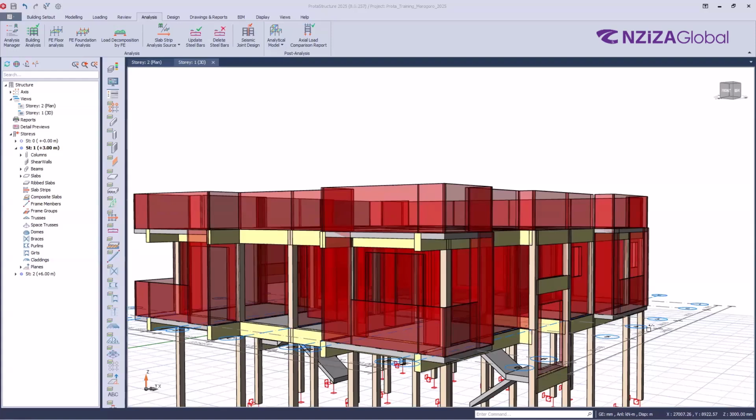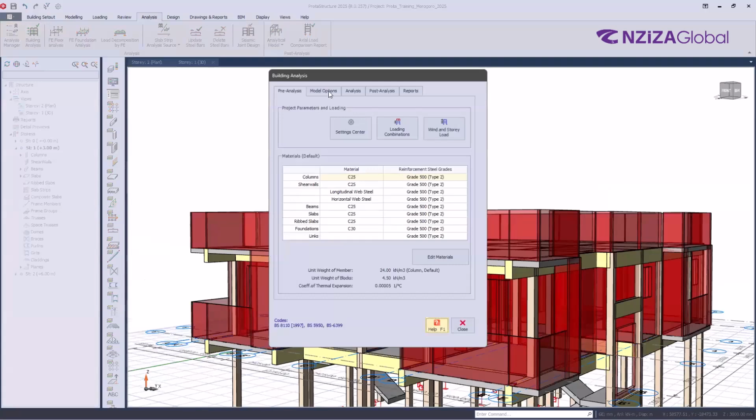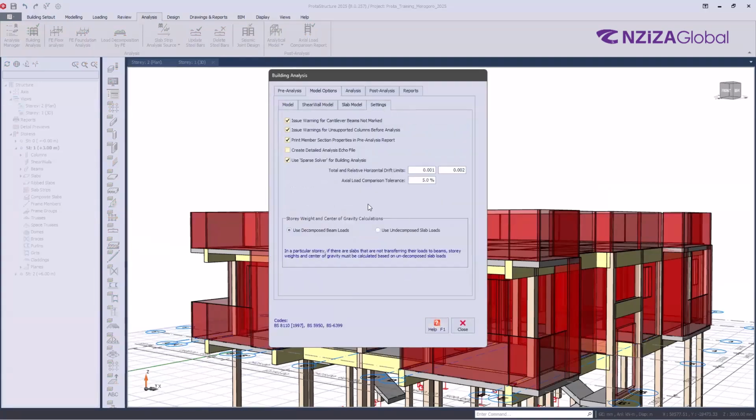The message is about the actual load comparison. You remember when we were talking about the settings you have to set here, under settings, the actual load comparison. The percentage that we set was 5%, and in yours I can see you have 5.5 after the analysis. It means the difference in loading has exceeded the 5 that we set. That's why you get that warning.